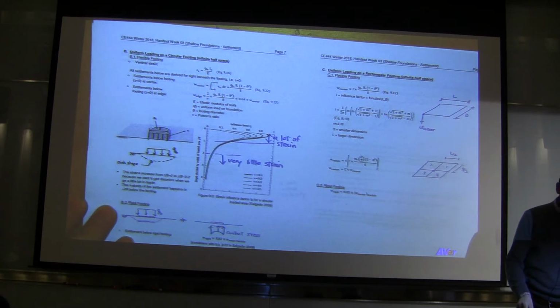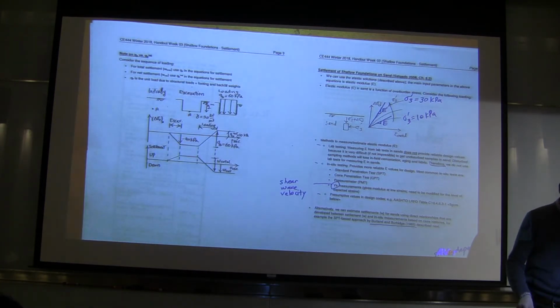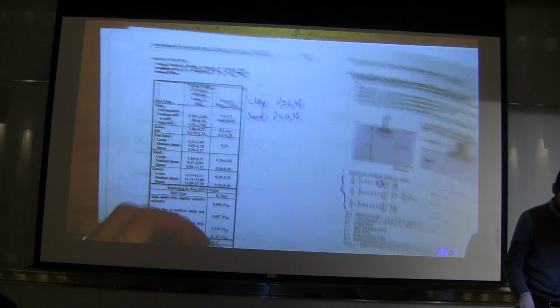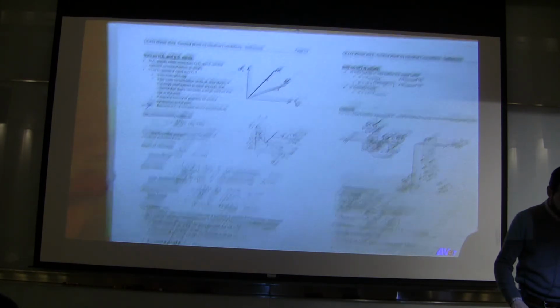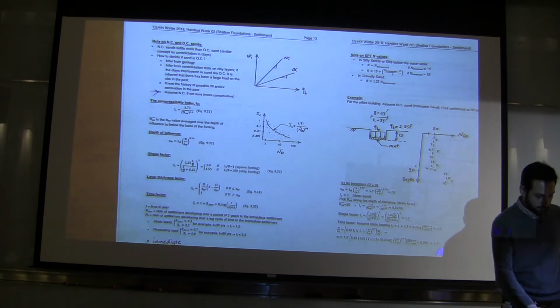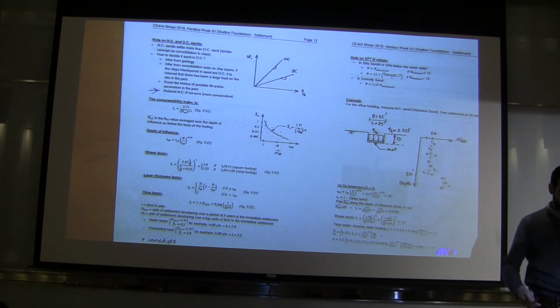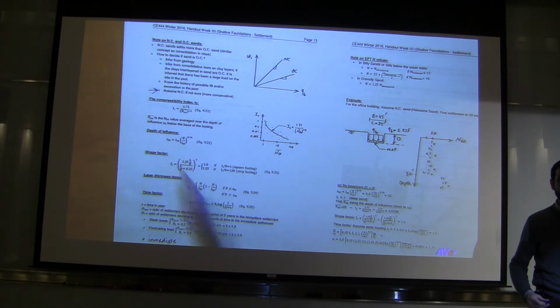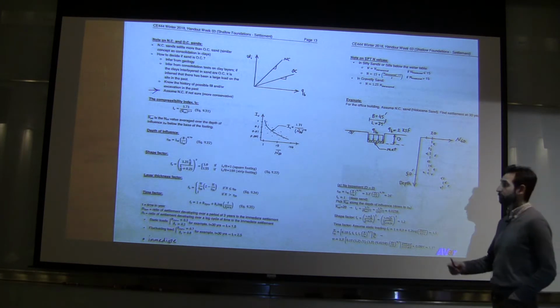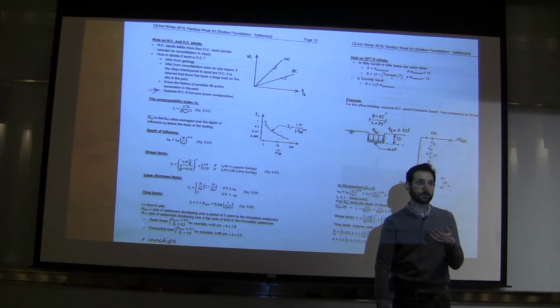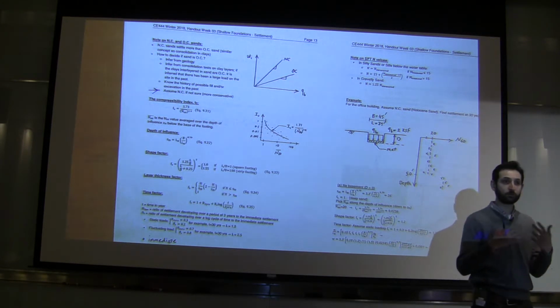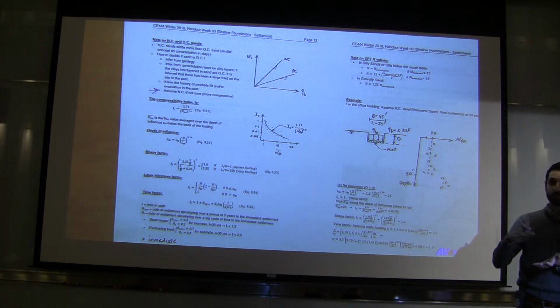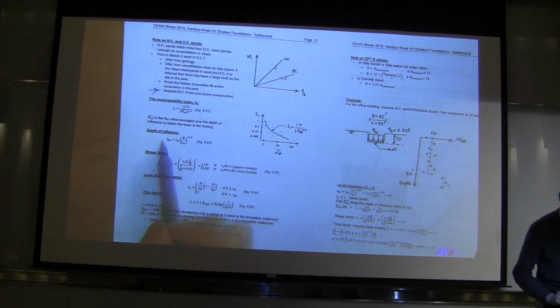So that is why, if I go back to page 13, the folks who developed these equations said, well, we want to have I sub c that estimates the elastic modulus, and we want to relate that to N60. But I don't want you to use the N60 that is really deep, that is not going to affect your foundation settlement. I want you to get the N60 that is representative of the area where you are getting most of your settlements. And that is how they came up with this depth of influence.